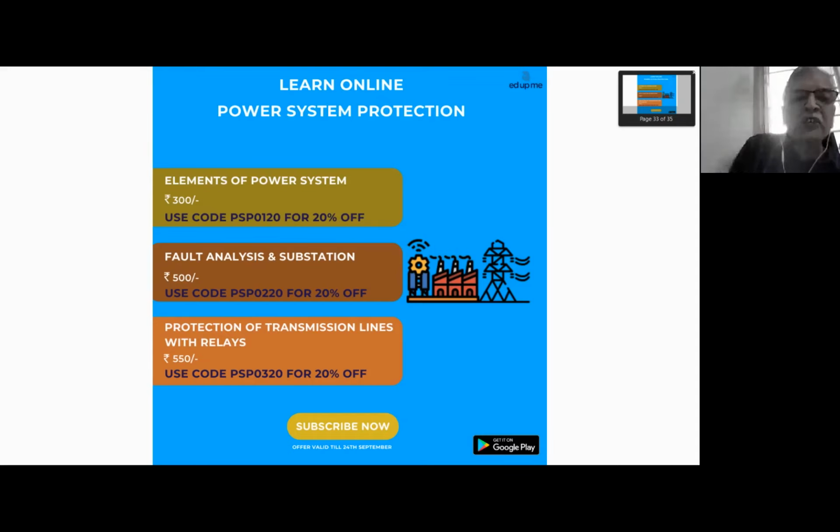the auxiliary switch of that breaker is available to us, because the breaker has 3 main power contacts plus 8 NO and 8 NC auxiliary switches. They are just mechanical switches. NO switches means when the breaker closes, that switch will close, and when the breaker opens, it will open. So NO and NC switches you can use in the control circuit, and you can give binary input to a numerical relay. When you give binary input, and if you have properly configured the binary input, it will change its setting to another one based on that tripping, that is, the switching available.